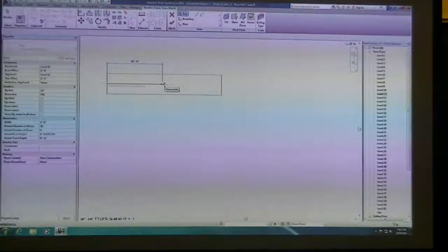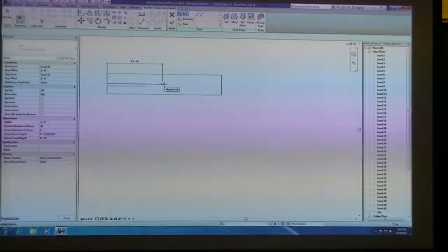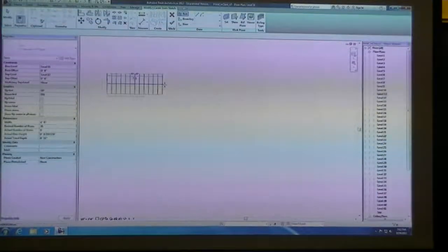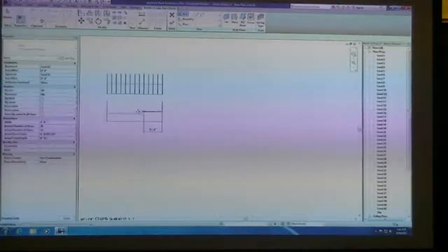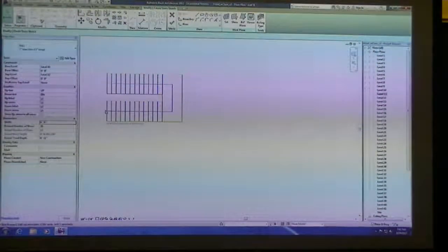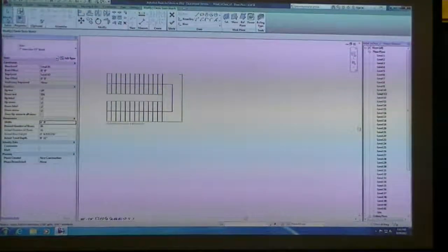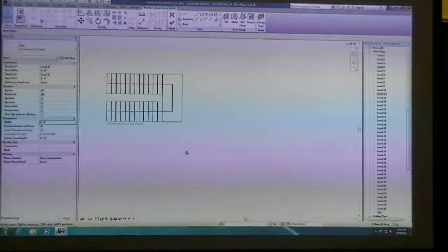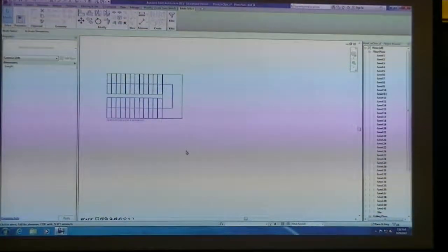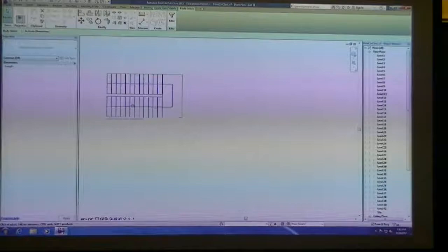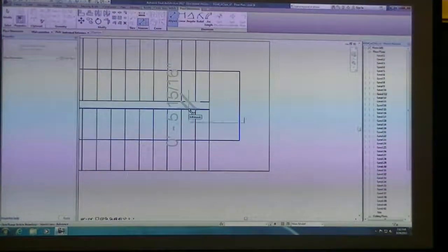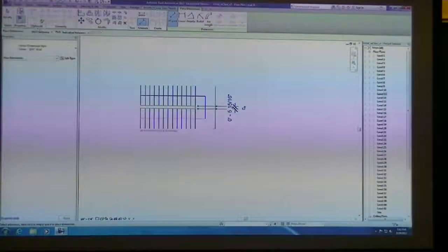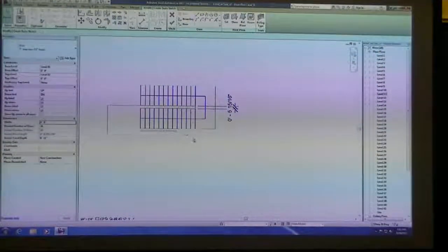I might go up until I get an equal, like 13 risers created and 13 remaining, and click, and then come over a little bit further and draw another set of stairs, and it creates a landing for you. Once you've done that, you can select this and move it in, give it some dimension, probably minimum dimension you want is like 6 inches between.